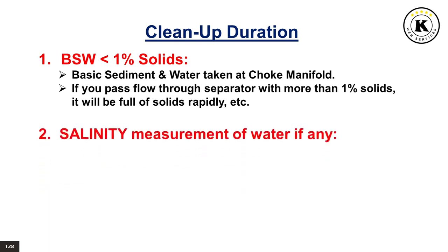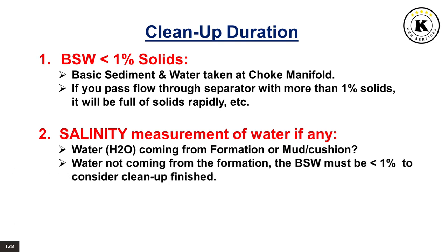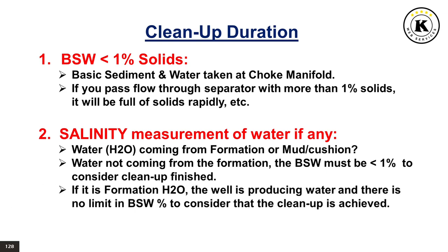2. Salinity measurement of water, if any. To confirm if water is coming from the formation, or is it mud or cushion. If the water is not coming from the formation, the BSW must be less than 1% to consider cleanup finished. If it is formation water, the well is producing water and there is no limit in BSW percentage to consider that the cleanup is achieved.